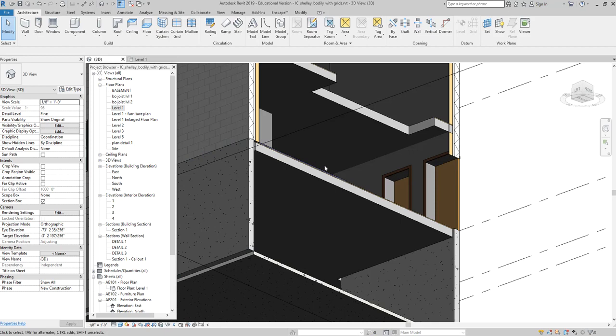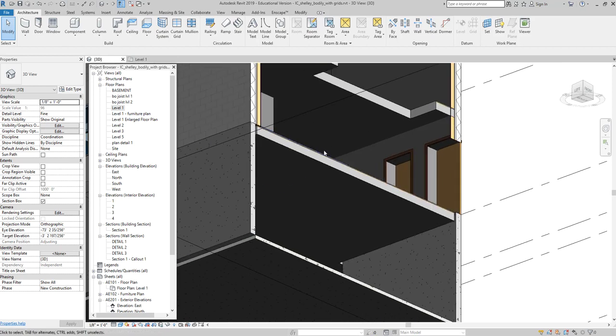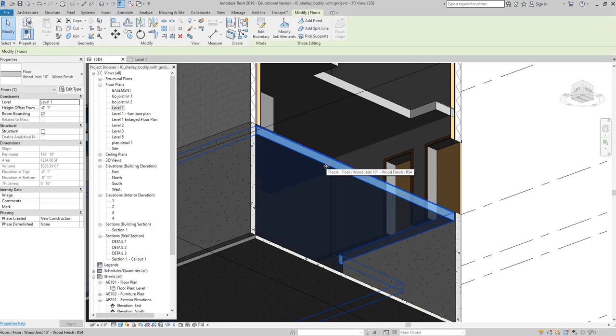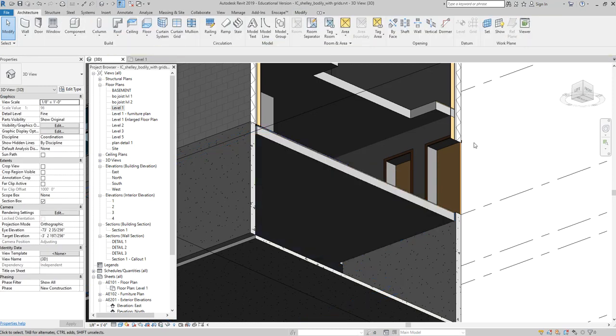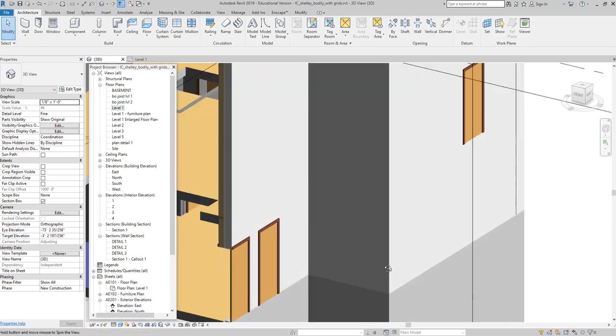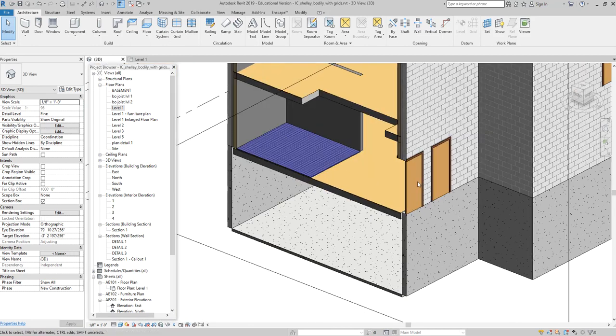Bless you. And the reason why my lights are not hosting into that ceiling is because it's not actually a ceiling, right? It's a floor. And it has gypsum board on the underside of it, okay? So when it's time to create ceilings and create lighting plans, you do have to go into your model and create an actual ceiling. You can't just place gypsum board on the bottom side of your floor and call it a ceiling, because those items won't host to that, right? So it's kind of my little caveat for the night. Make sure that you always put an actual ceiling in your project, okay?